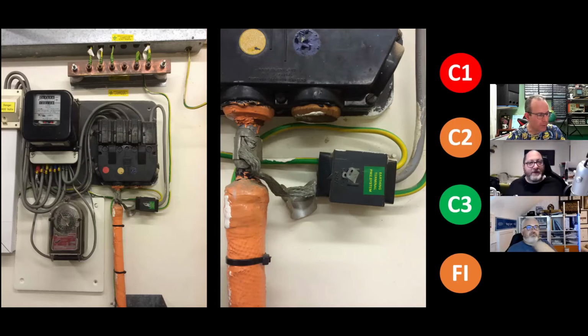And yes, neutral currents from imbalance or harmonics would now be shared on the neutral and the sheathing. Yes, they certainly will. So yeah, PME and TNCS in general is absolutely hideous for EMI. It's pretty much the worst possible choice you can actually have. So if EMI is an issue, you don't want TNCS in your building.